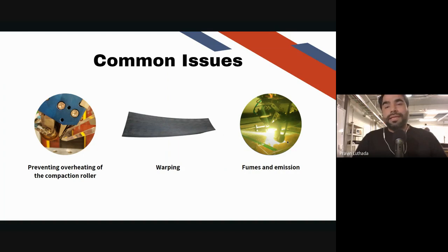And just to release these thermal stresses, you would want to run it through a secondary process of relieving the stresses in an oven or autoclave, or whatever you have at your disposal. And that is the only way, I think, to get rid of them. Unless you're doing closed geometries, where there is a possibility to get better results, but still there could be some internal stresses that you would want to relieve.